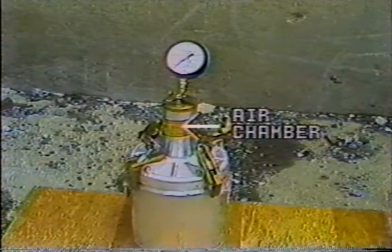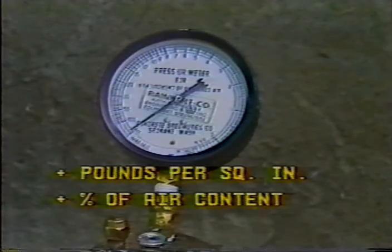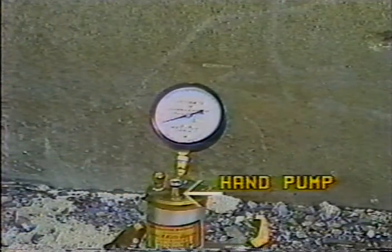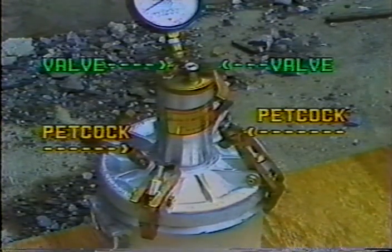Above the cover is the air chamber, and attached to it is a pressure gauge, with a dial graduated in both pounds per square inch and percentages of air content. There's a built-in hand pump for building up pressure. The valves and petcocks are for adding and draining water and for releasing pressure from the air meter.